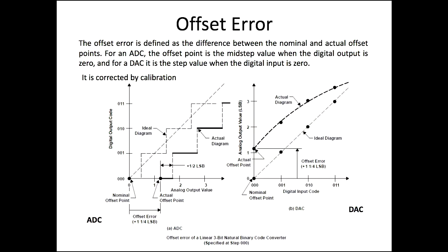In the ADC, you have to do the same. You have to vary the voltage at DC. You should be checking the ADC with a DC voltage. When you put 0 volt, you see all are zeros. Then if your LSB is, in an exaggerated version, equal to 1 volt, you have to vary up to 1 volt. Immediately when you cross 1 volt, it should jump to 0 0 0 0 1. If it is not getting like that, then you should understand there is an offset. So you can find it out when you apply a DC voltage.